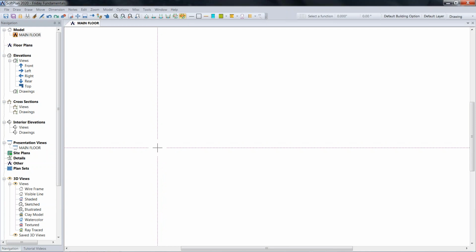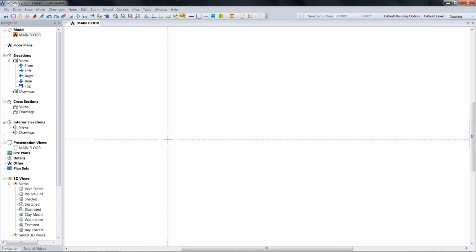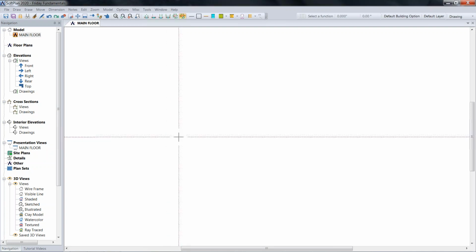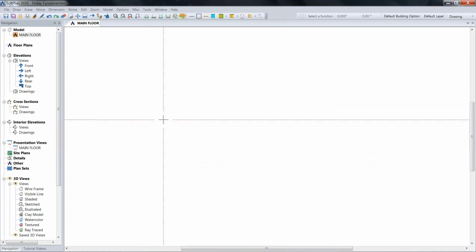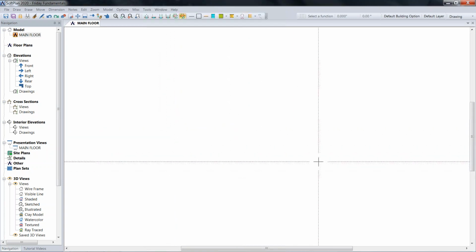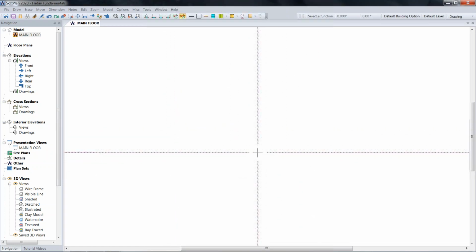So the base bottom floor is going to be concrete block, 9 feet 4 inches tall. It's done at 9'4" because of the block size increments. And then we'll put a web floor truss between the floors. We'll put a 2x4 wall on the second floor with stucco as well. And then we'll pop a quick roof on it, and then we'll go from there. And then I'll model it for you in section, elevation, 3D modeling, and then we'll run a quick bill of materials.